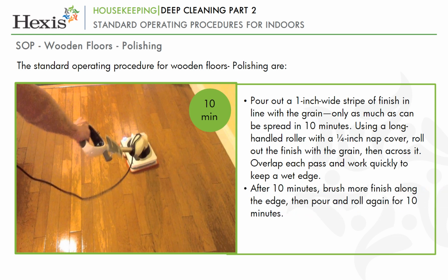After 10 minutes, brush more finish along the edge, then pour and roll again for 10 minutes. Continue until the floor is covered. Wait 3 hours before recoating and a week before putting back furniture.